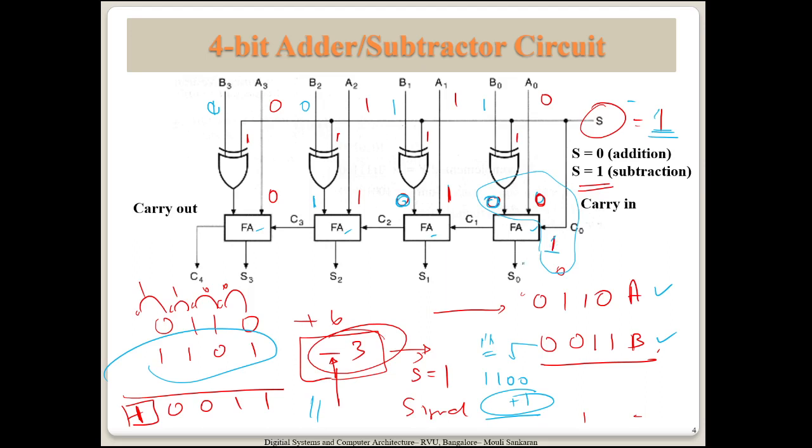So this is going to result in addition of 1, result is 1, carry will be 0 because we are adding 1 and 0 0. Now this is again going to be sum is 1 and the carry is going to be 0, and we have 0 1 1, so that is going to be 0 here and carry will be 1. And what is the input here? We said that it is 1 here, so this will be 1 0 1, so this is 0 and this is 1. Now what about the carries?